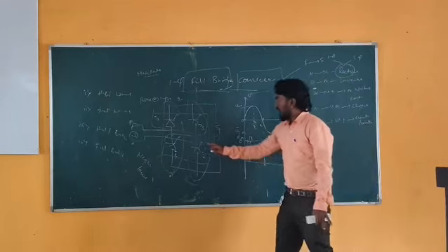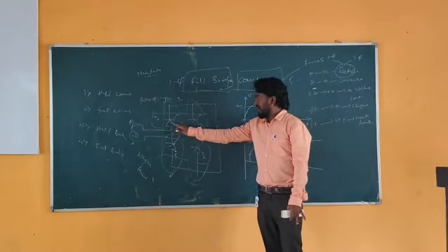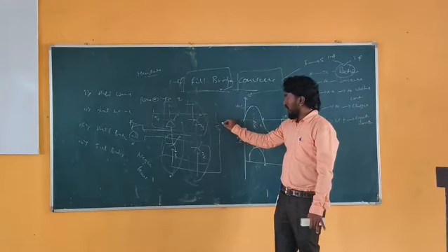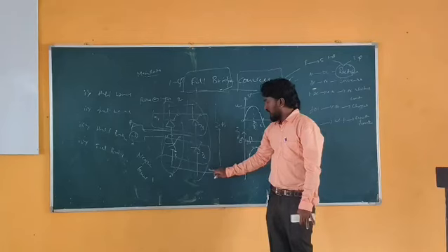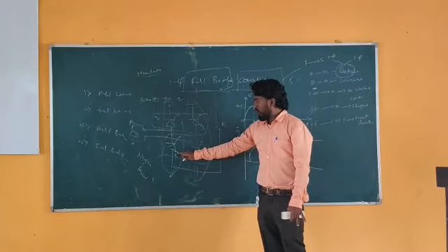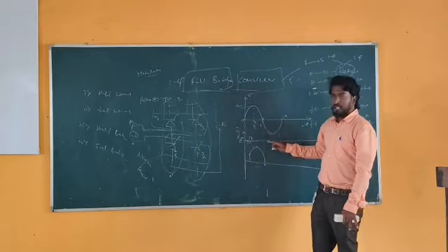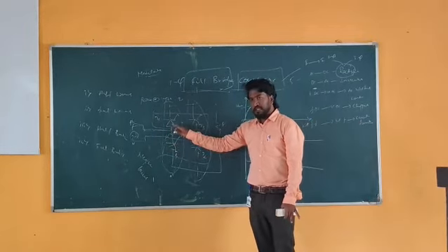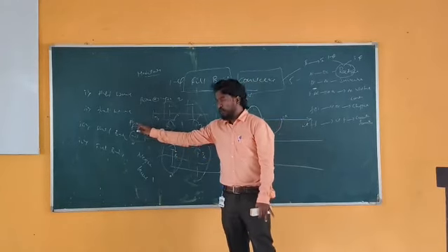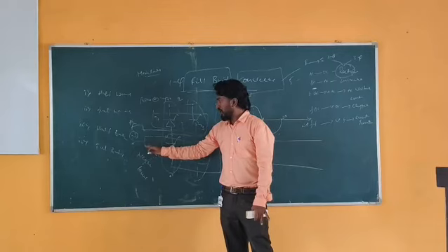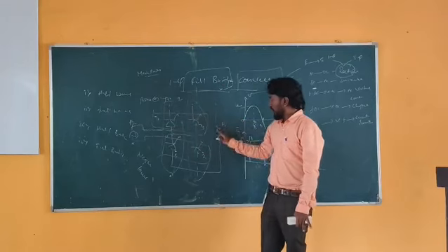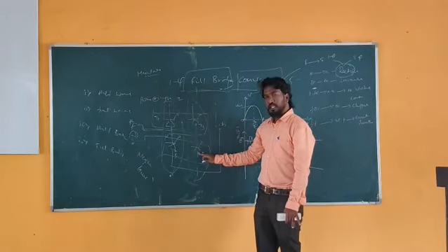After the thyristor T1 is conducting, the current will flow to the load RL. Then it will go to T2. It doesn't go to T4, because we already know we need to follow a condition that no two thyristors in the same line should conduct. The current always goes from high potential to low potential, so it will take the path from phase to neutral through T1, the load, and we mandatorily need to give the gate pulse to T2.